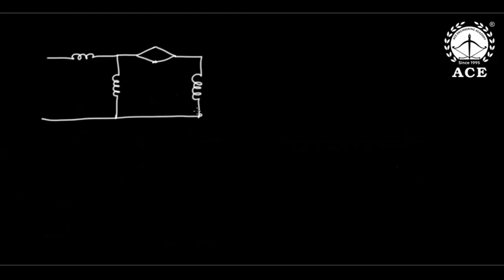So here, if I apply Ohm's law, now watch this, please. But the only difference is you cannot give a DC signal here, because if you give DC signal, inductor acts like a short. So you have to give a time varying signal and apply Ohm's law. So this is 5 Henry, this is 3 Henry, this is plus and minus 2 di by dt, this is I, and this is automatically 4 Henry. Now I will apply Ohm's law.